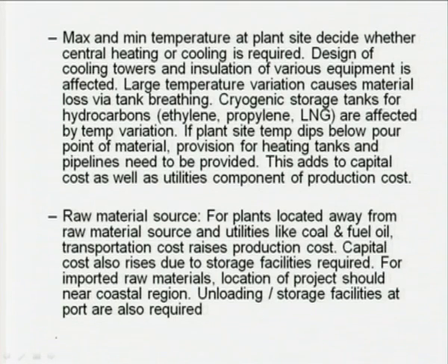If the raw material sources are away from the manufacturing site, then the inventory of raw material and those required for utilities, such as low sulfur heavy stock or fuel oil, would be higher. Okay. So, that would add to higher capital cost for the storage tanks as well as warehouse. Working capital requirement will then go up.